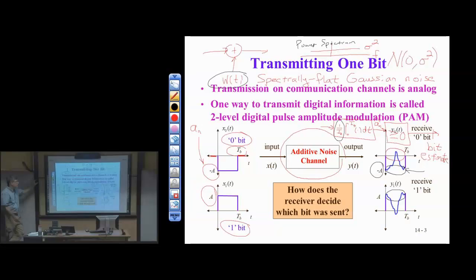And by best here we mean it maximizes the signal to noise ratio after this averaging operation is done, which is really what it is: average over the symbol time and just take one value. It's just one value coming out of that for the symbol time. So it's the best thing we can do in terms of the signal to noise ratio at the estimate here, A sub n hat, or A hat of n. Okay, we'll show this in part 2.